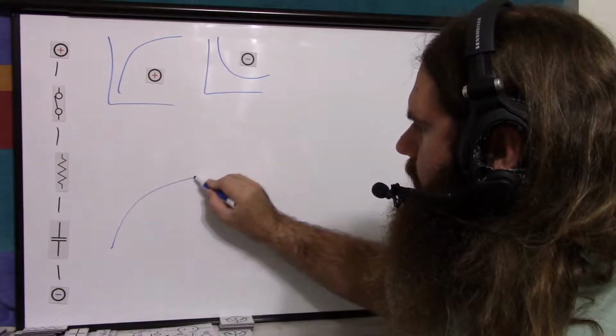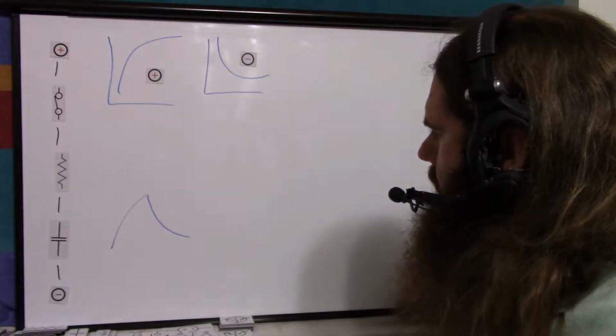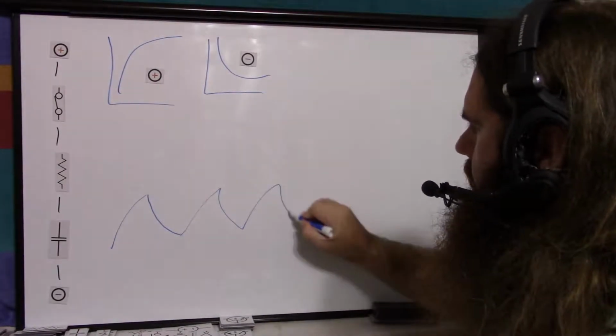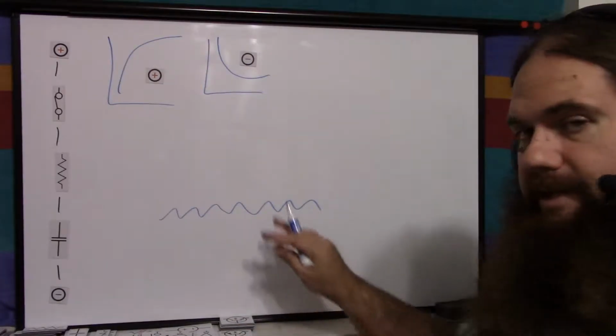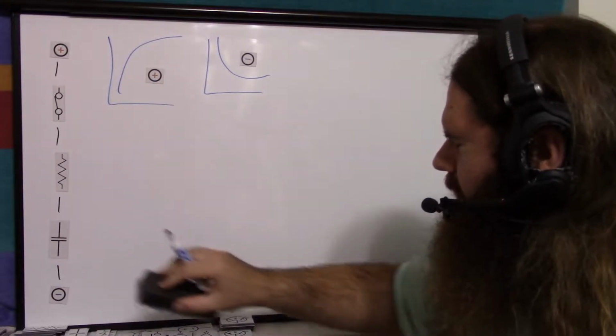What happens if you abort? So you want to charge it all the way, but you stop. And then you want to discharge it all the way, but you stop. And then you start charging it again. It gets sharper. What if you only let it charge a little bit? See, the amplitude's lower, it's never charging up enough, but it's getting to be a rather sawtooth thing.